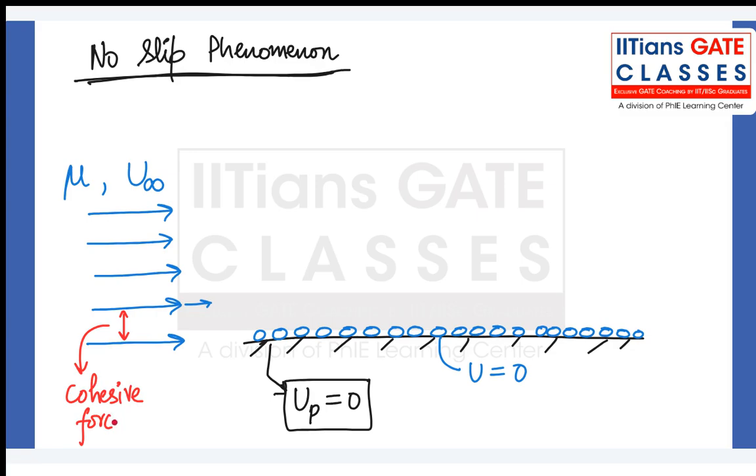Cohesive forces means forces of attraction between fluid particles. So each particle attracts the particles surrounding it. The fluid particles at the top will try to flow with velocity u infinity, but the bottom particles are at rest, so these particles will pull them towards the plate a little bit.